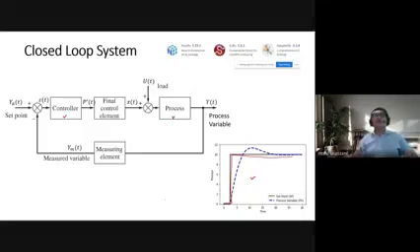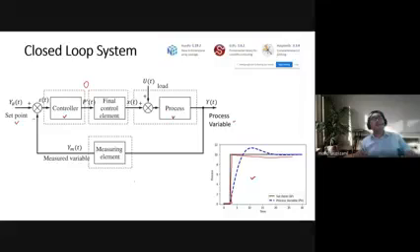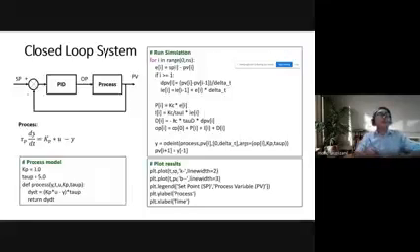All right. So just the same like this. A process variable, set point, and then in this case we will have O as our control output. Okay. So we use SP, OP, and then PV. In this case, I just use a most generic process. So tau P, tau process, and then KP, and then U is the input to the process, and Y is the state here.